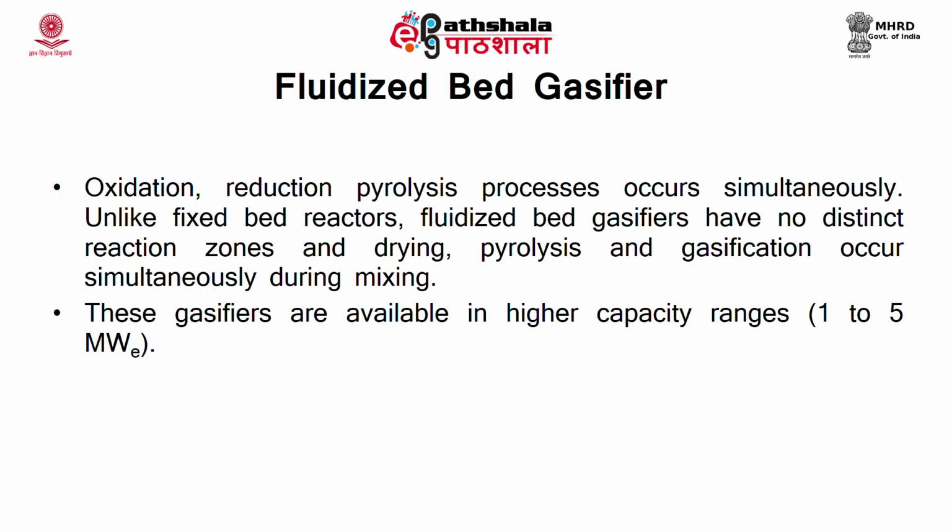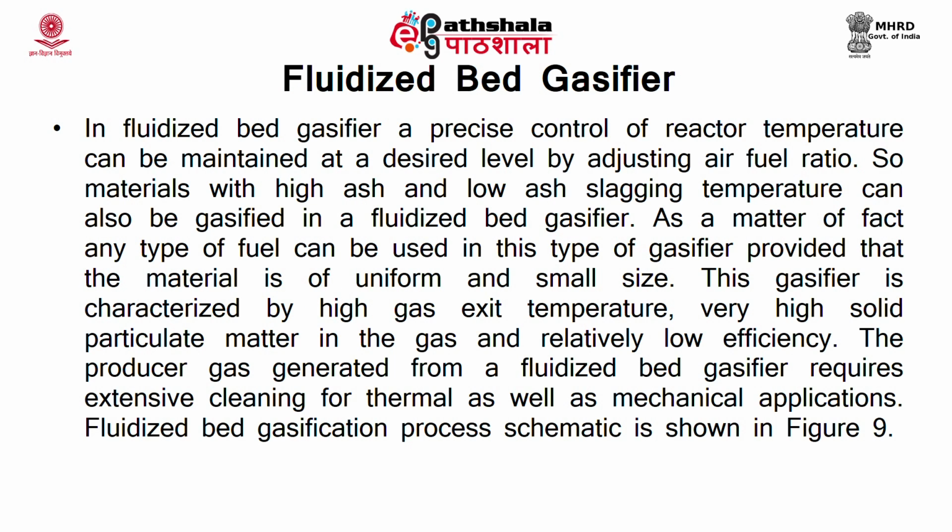So, in this gasifier, oxidation, reduction and pyrolysis processes occur simultaneously. Unlike a fixed bed reactor, this gasifier has no distinct reaction zone and the drying, pyrolysis and gasification occur simultaneously during the mixing process. In a fluidized bed gasifier, precise control of reactor temperature can be maintained by adjusting the air fuel ratio. So, materials with high ash and low ash slagging temperature can be gasified in this type of gasifier.